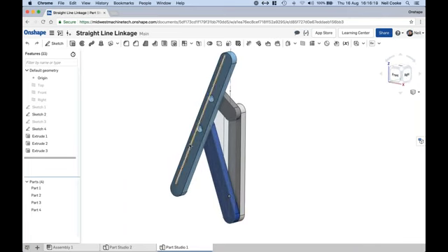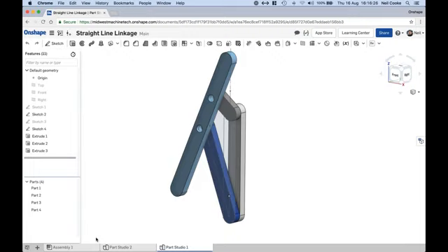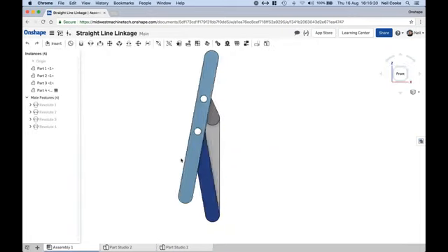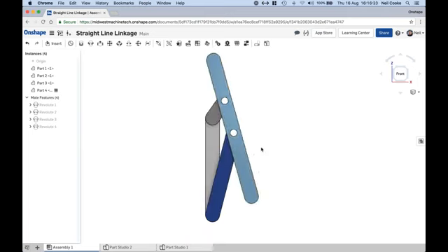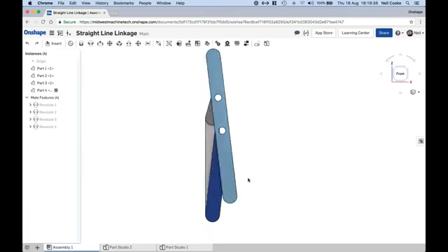That will give you the profiles. In fact, you can see from here we have sketched it in the very same way, created 3 extruded profiles, and then you must take it into the assembly to add the revolutes and any other constraints or mates to actually make this thing move.